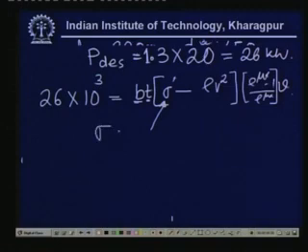The actual value of sigma dash is sigma multiplied by the angle of wrap factor, and the other factor is the speed factor, if it is done at some other speed. So that was the speed factor. Please have a look at this actual expression in the theory we have covered.